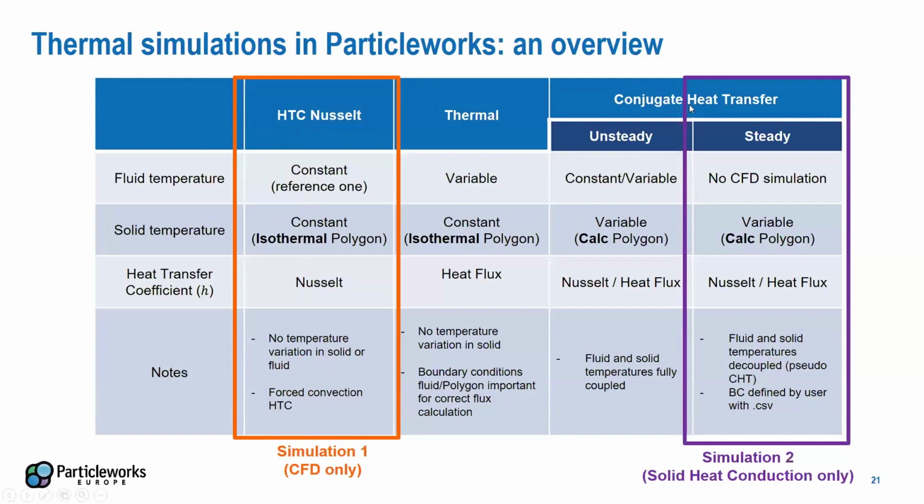And we can transfer those maps as CSV files to a solid heat conduction model that is basically the same model used for the CFD simulation with just a couple of variations of the numerics. So effectively, we use the same model both for fluid simulation, but then also to estimate temperature in the solid while considering the heat transfer boundary condition and also possible heat losses, okay?